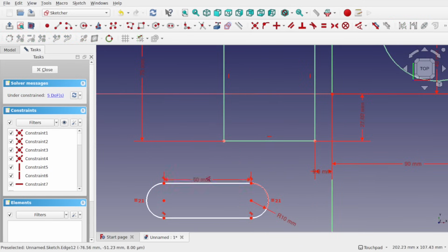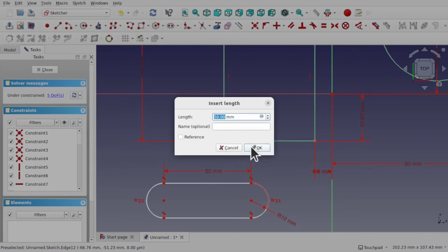Use dimension in. I can click it and then click the dimension as you saw there. So I can click that line and we have that option there, click that dimension in. And if I hit M on the keyboard, you can see we get a horizontal constraint. If I hit M again, we got the vertical constraint. M again, we got this constraint here, which is the block constraint. So we can cycle through those constraints there.